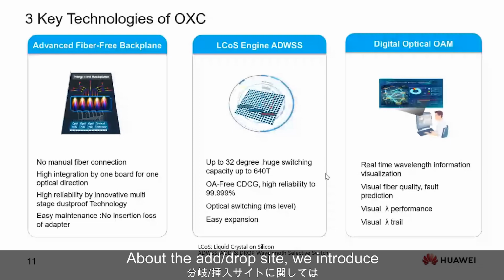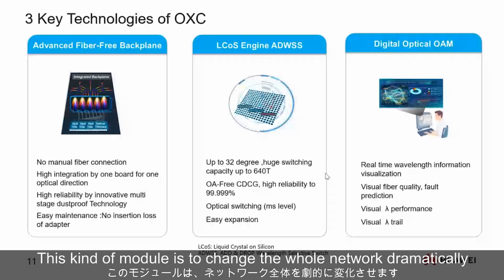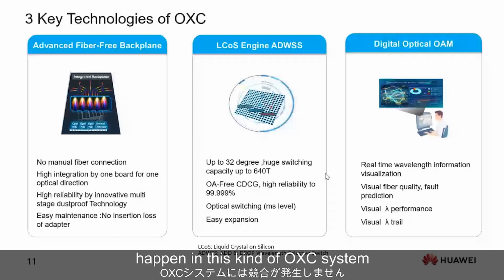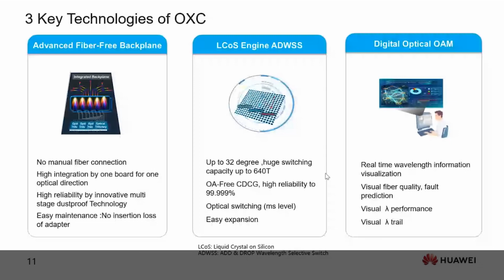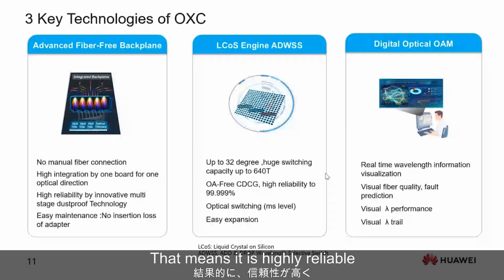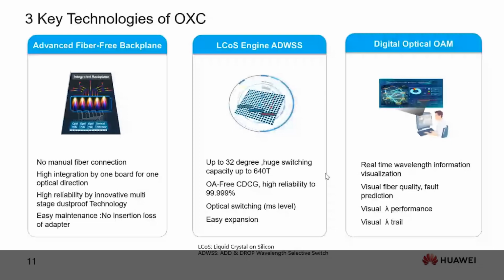About the add-drop side, we introduced the LCOS liquid crystal on silicon based add-drop WSS. This kind of module changes the whole network dramatically. That means there is no contention in this kind of OXC system, and also there is no optical amplifier. So it is highly reliable and also easy to expand the add-drop ports.